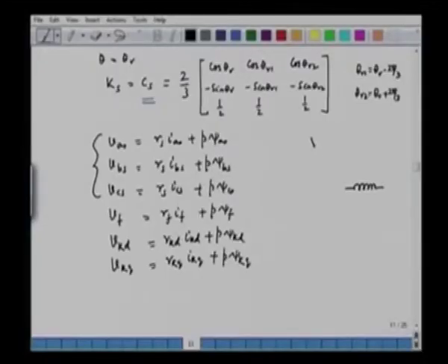But before we go for the rotor reference frame, let us try to understand how the machine is simulated in the ABC variables. Physically, we have phase A, phase B and phase C. We have 3 windings in this case. These are the stator windings, AS, BS and CS, and each winding has an applied voltage. For example, in phase A we have VAS and this is IAS.